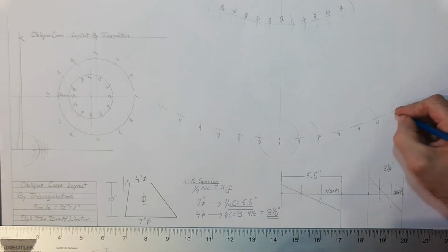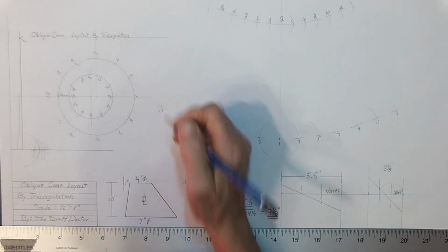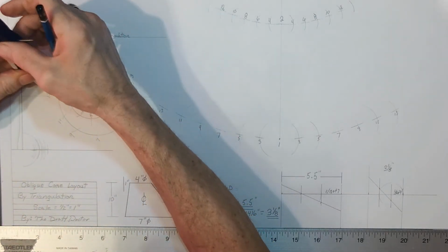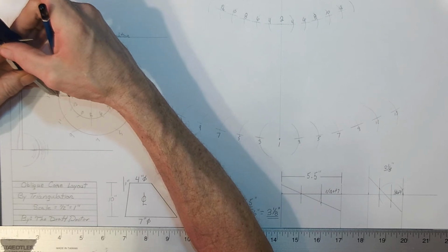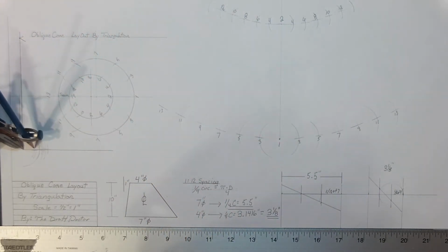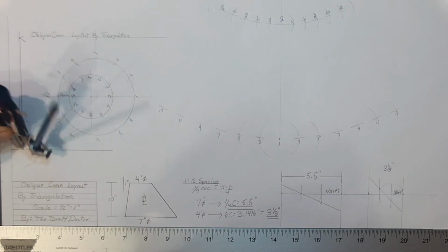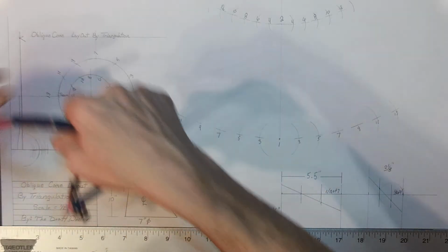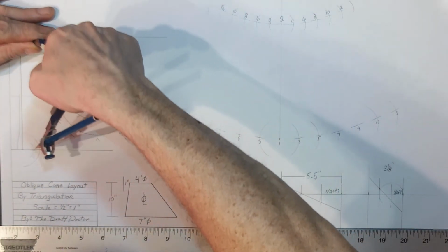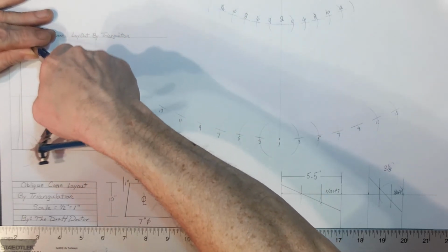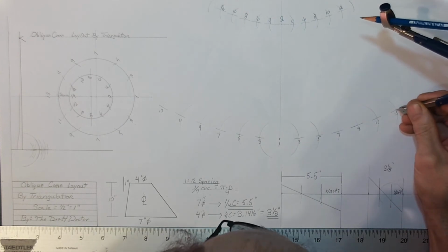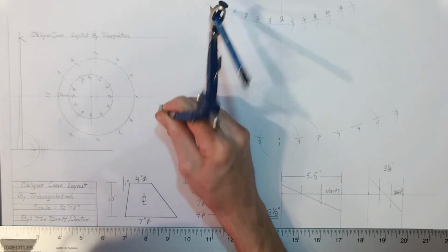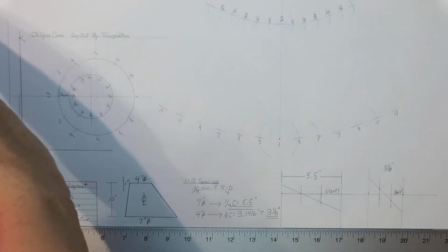Document. 13 to 14. 13 to 14 is my seam. My seam is not straight up and down from each other. It is offsetting by the 1 inch as required on my working drawing. Here now is my plan length. I have to triangulate to find a true length of that. And that is right here. True length of 13 to 14 is this. And now I have point 14.